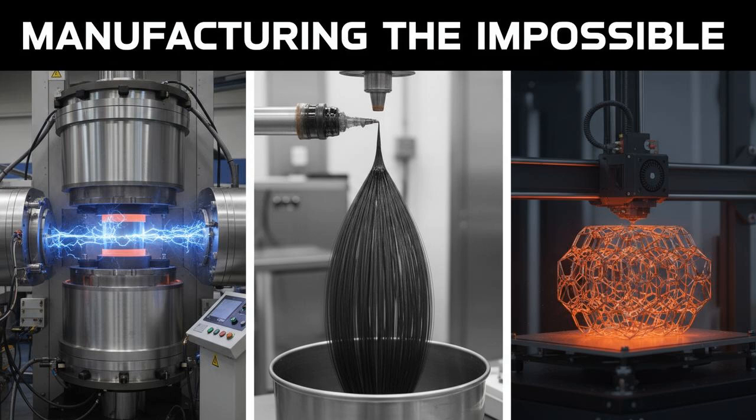Traditional ovens take hours to bake ceramics. SPS pulses massive electrical currents through the ceramic powder, heating it to 2000 degrees Celsius in minutes while applying tons of pressure. This fuses the atoms instantly, without allowing time for grain growth, keeping the material strong.